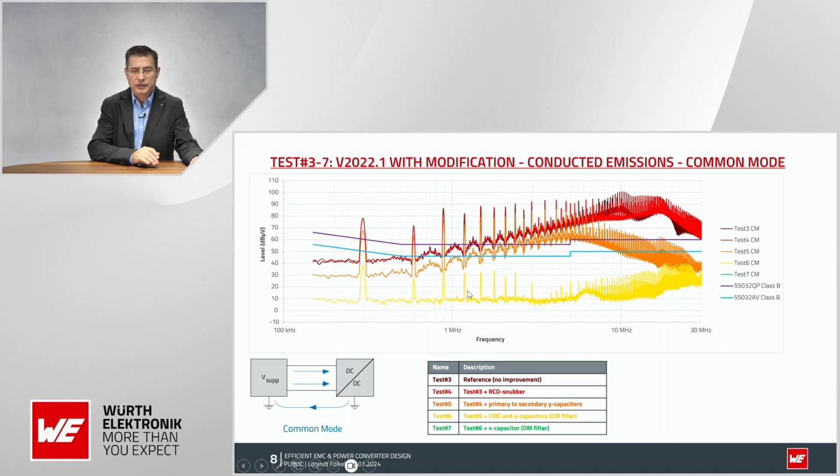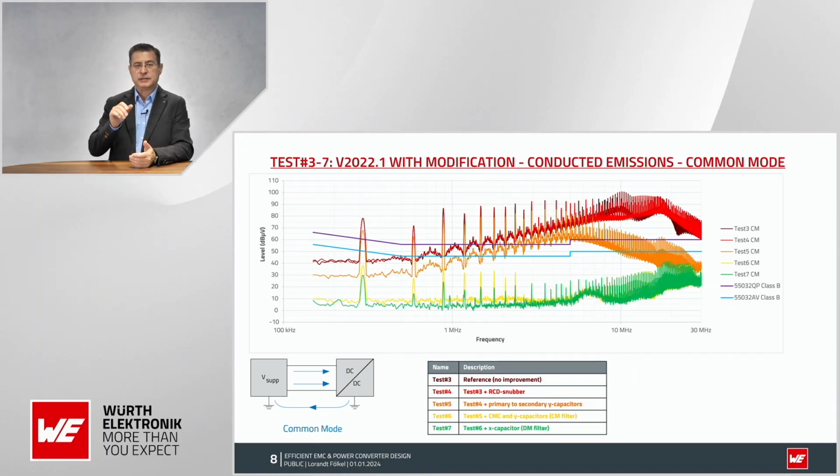When I activate the X capacitor, it makes a short on the noise, so it turns this noise back to the flyback, and you don't have the common mode noise outside of this device anymore. Every common mode noise is somewhere happening in a loop where it's a differential noise, and if you can cancel that fast enough and close enough, then you will not have to fight common mode noise. So this is common mode noise.